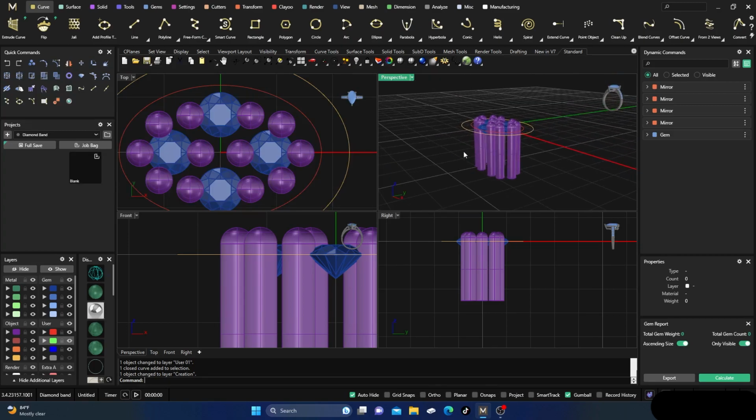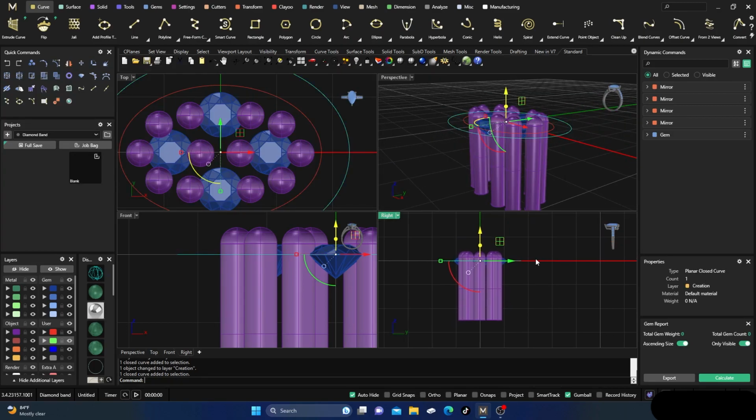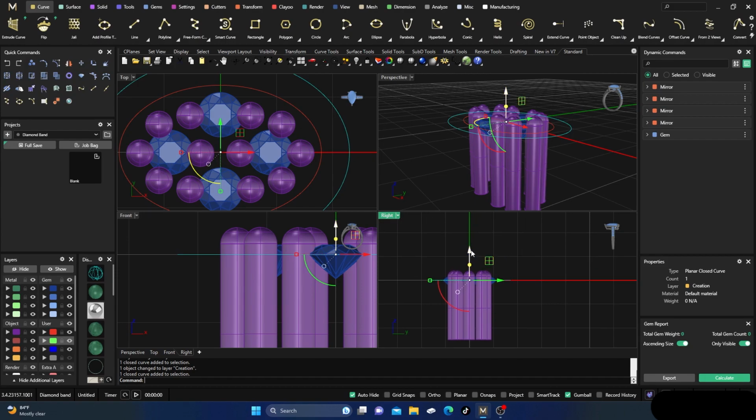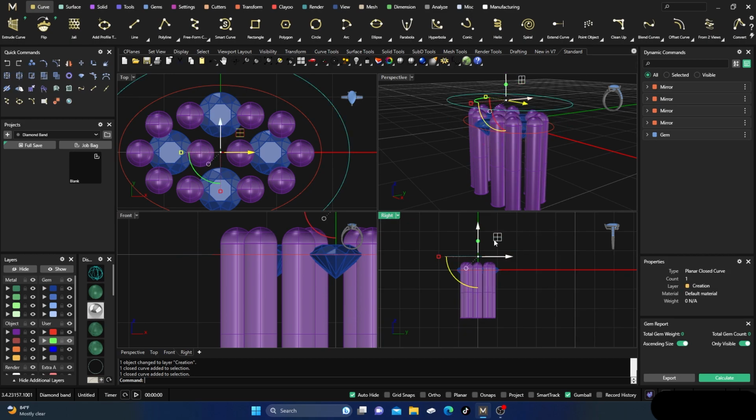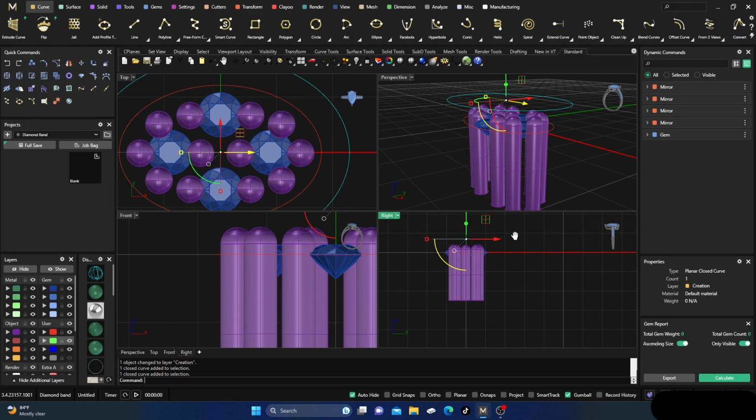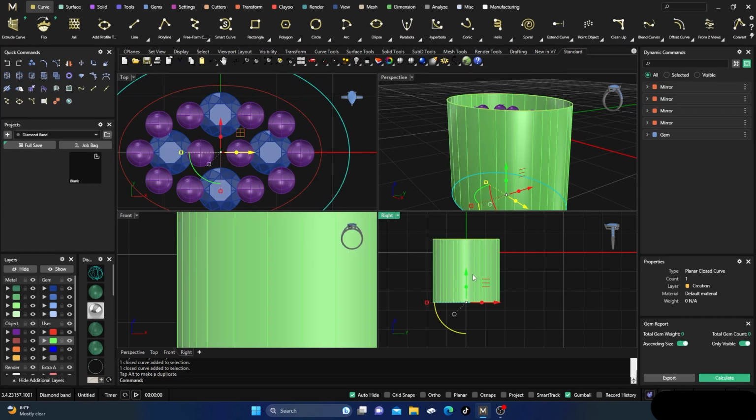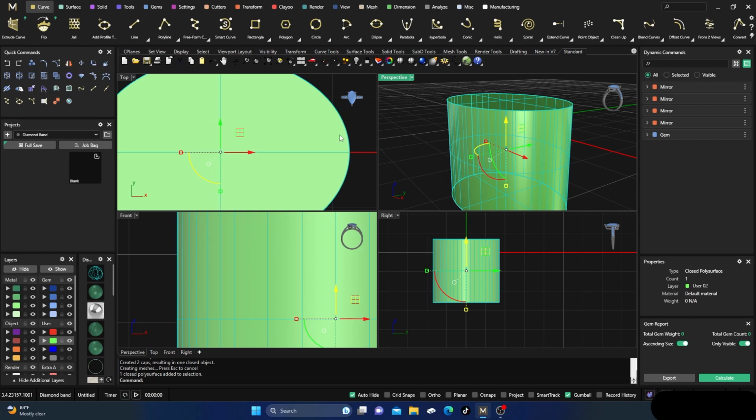Now what we want to do is take the yellow one and bump it up a little bit more than normal. Okay, I have a 0.6 in there. Let's go 0.7 just to be safe. And then hit enter. So it'll bump that curve up, right? And then I'll select that curve. And now I'm going to grab that ball and just drag it down to give me a surface just past my prongs, just a little bit. And then click off it, click on my surface, CAP, and enter. And then I'll just leave that there.